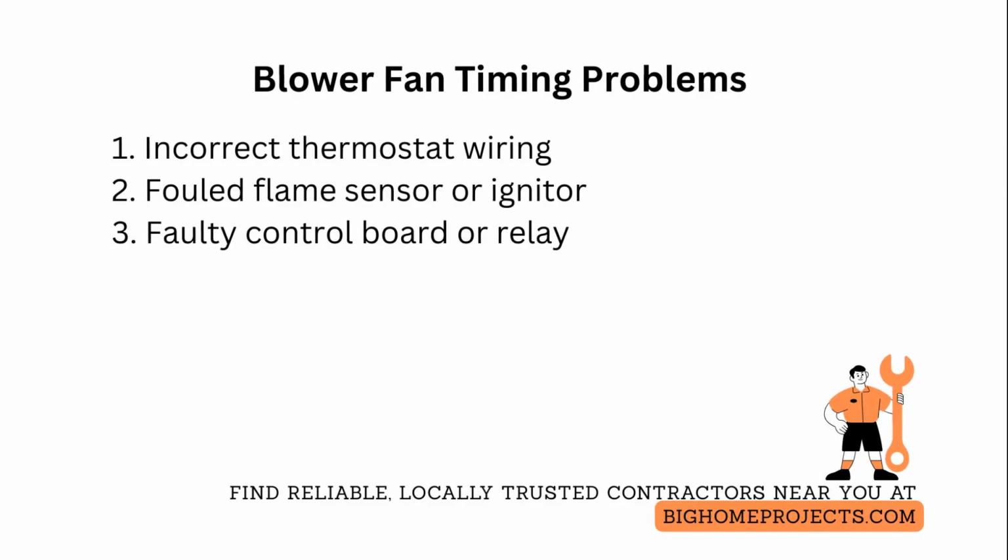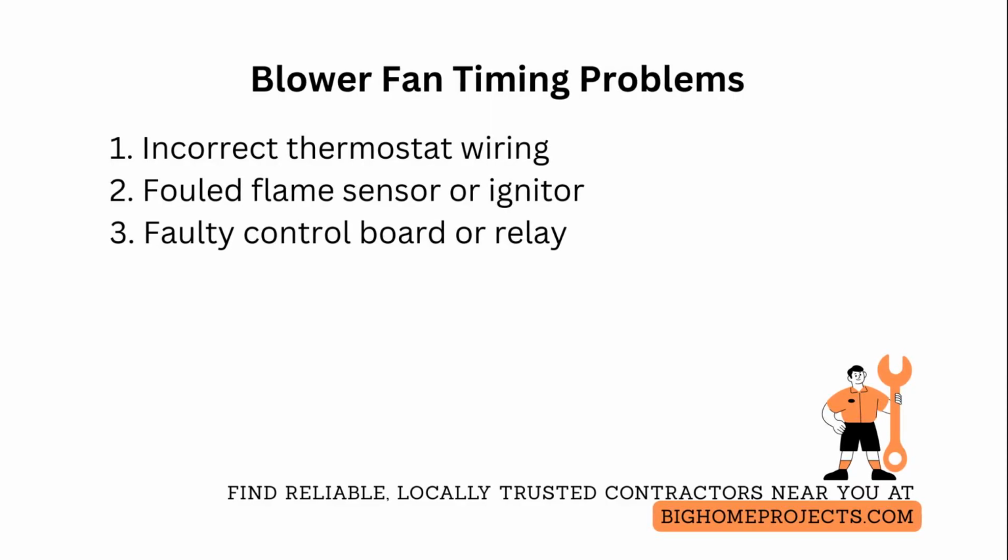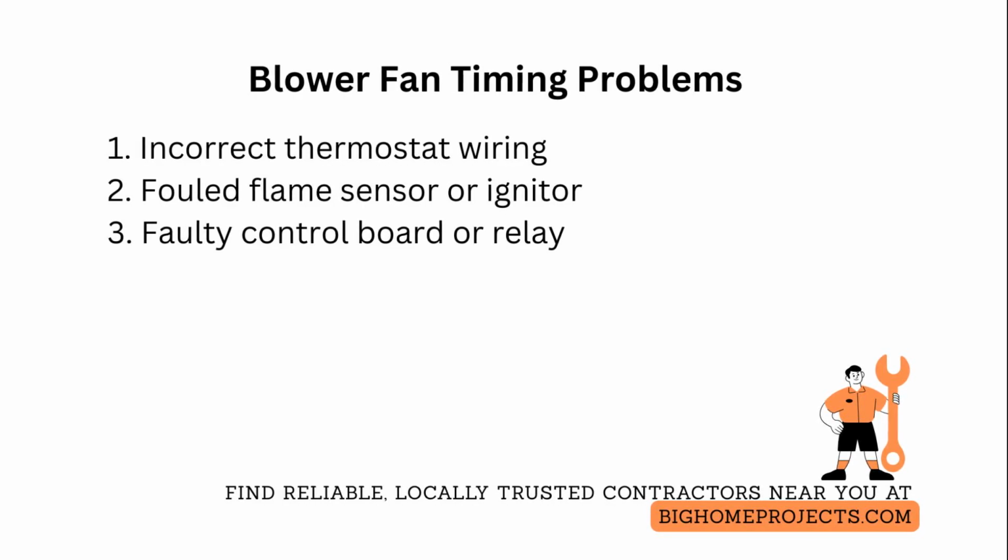The third typical issue is a bad control board or sticky relay creating premature blower activation. Replace the control board or relay with the exact OEM replacement and test sequence timing with a stopwatch and a multimeter.